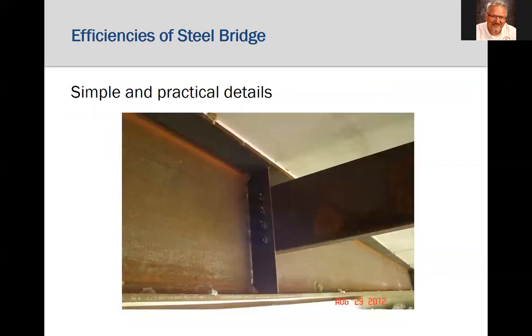We talked in lecture 1 that steel is a versatile material and that steel bridges can be made in many forms with complicated details and fabrication. However, for these simple bridges, they do not require complicated stiffener and diaphragm details. Simple details like shown here, which is just a channel diaphragm, are cost-effective and easy to fabricate and easy to erect, which cuts costs.